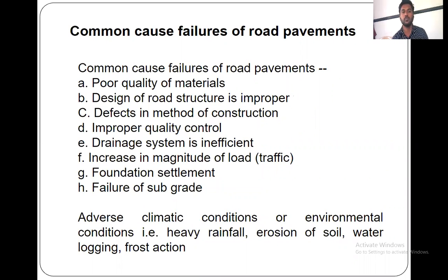Then there are some common causes of failure: the poor quality of the material. The main important thing is that whenever we are using material for maintenance, suppose there is already a concrete road and a pothole or crack on that road. Whenever we go for the maintenance of that road, we should use a higher grade of concrete to fill that pothole.